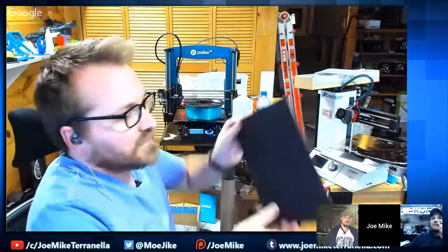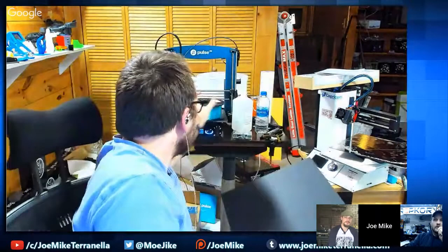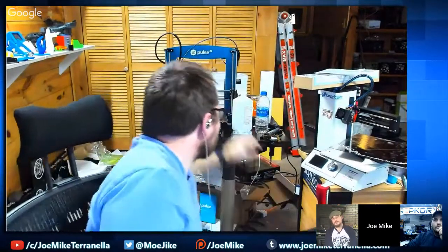So here's my build tack flex plate, and the one that came with the Pulse has Garolite on one side, and then I put PEI on the other side. That's the one thing I love about the flex plate system and the plate systems on the Prusas: all these plates are interchangeable because they're all pretty much the same bed sizes. It's awesome. I love this so much. It's great being able to swap it out whenever you want and experiment with different things and not have to worry about ruining your printer.